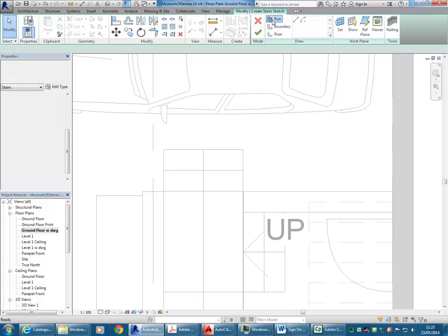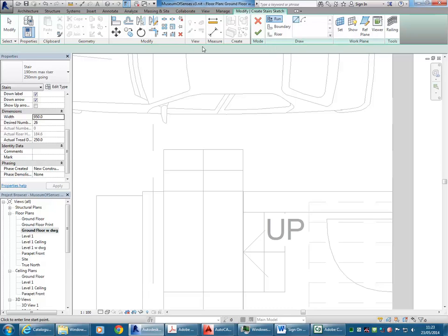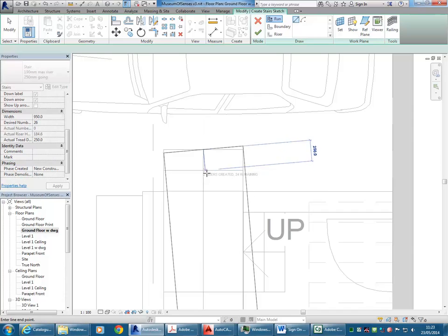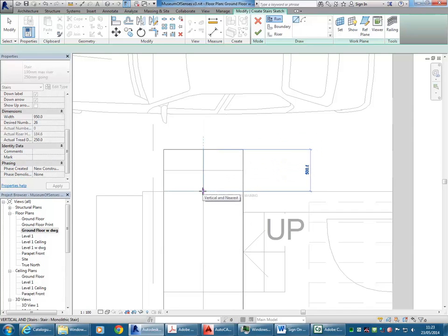And then using the run tool, notice it's on 26 risers in total. I'm going to do just from the midpoint of this line, so I'm going to type SM and then click on the line, and then coming down to the line below, I'm just going to let it give me just the 2 risers. Sorry, 3 risers it's going to give me.